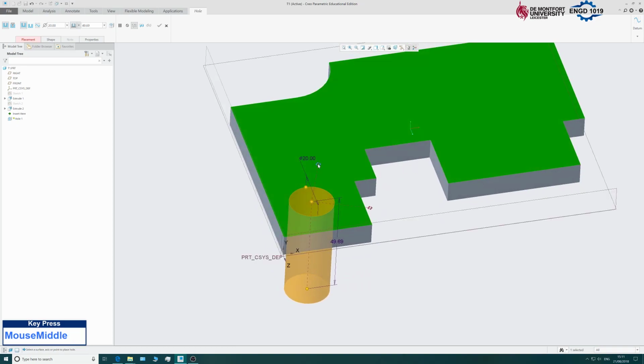So if I click this one here with the left mouse button, then drag whilst holding the button to a face, you can see I'm connecting it to this face over here, and the square completes. So it's broken, and then you attach it to a face, and it becomes complete. And it then puts in a reference dimension for you.